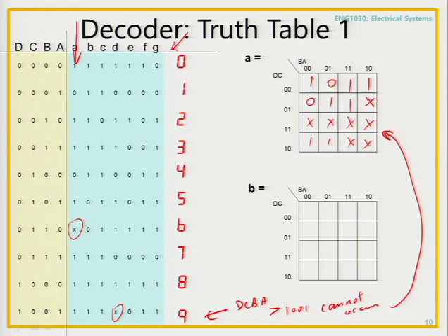So using don't cares helps because it helps you to make bigger boxes. So for example, over here I can make some really nice big boxes. I'm going to make a big box here. I can make a big box here because of all those don't cares. I can use don't cares here to make a big box, and I can use don't cares here to make a big box. Right? That's great. But if you do happen to get a code or an input which is out of what we've specified, your outputs will start to get a little bit weird.